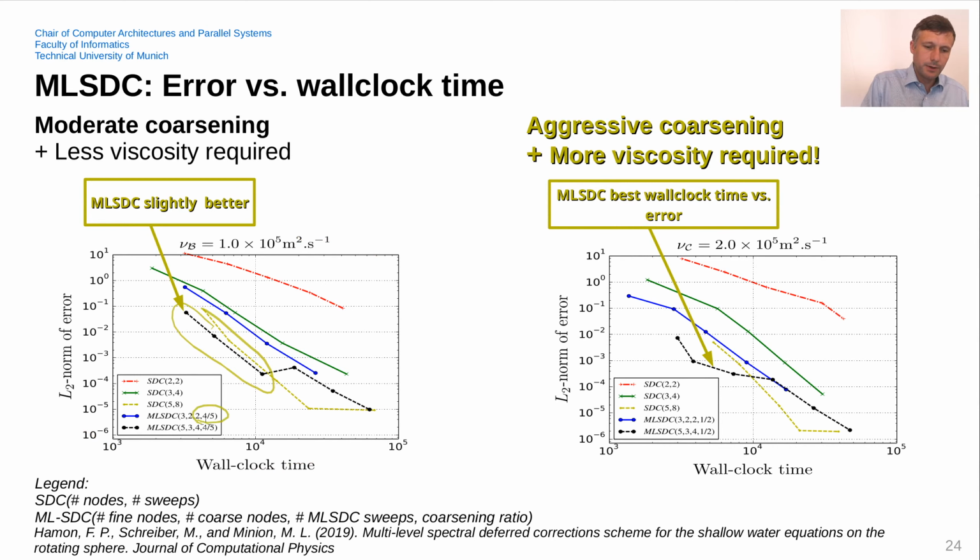So in this case, we only used 4/5 coarsening, and this is now where we use half of the modes in our solution. But then it also turns out that if we use a stronger coarsening, I assume it's the lack of the nonlinear interactions that requires us to add more viscosity to stabilize the solution.